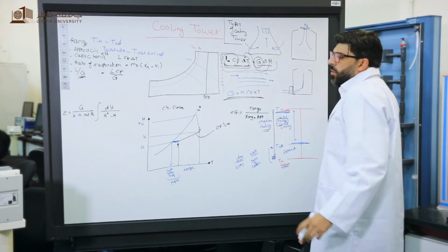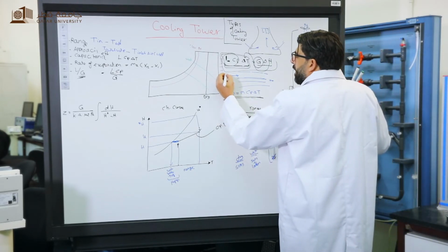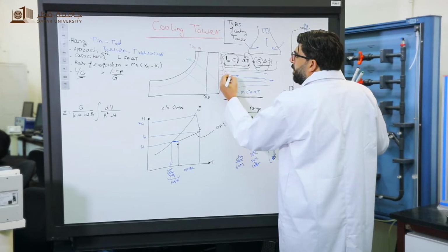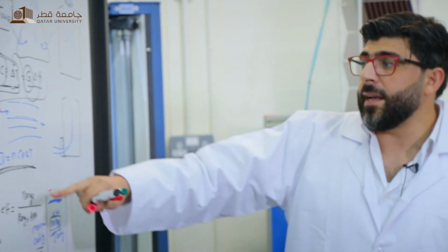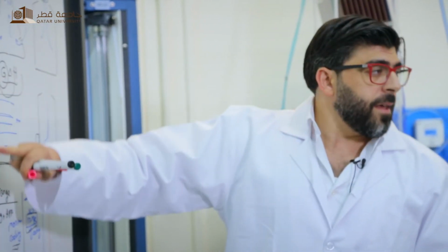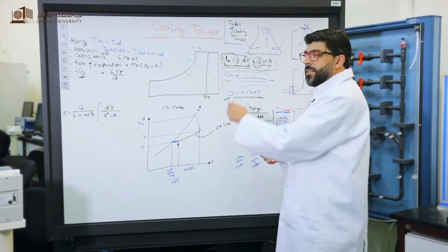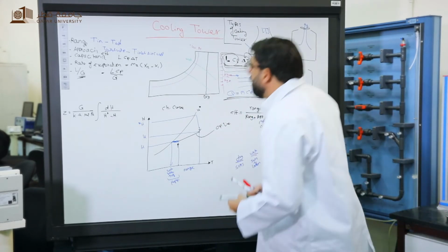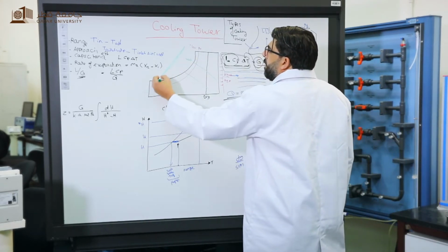It is also known as humidity ratio, and it is equal to kilogram of water per kilogram of dry air. Or in some psychrometric charts, you can find it as gram per kilogram. So just make sure you read the units correctly. Also, we have enthalpy. Enthalpy is here.